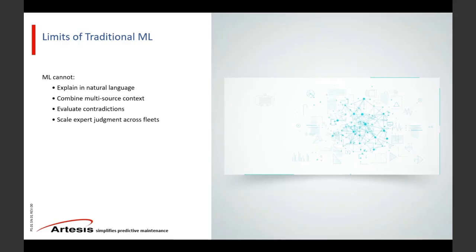It also doesn't automatically combine the multiple signals that our electrical signature analysis-based solution generates into one narrative. Meaning that you will sometimes have mechanical issues. You would see a bearing fault, but if that comes from fluting, which is caused by a VFD, it requires a more comprehensive look into multiple data sources to, again, create a single narrative. In real life, you're not looking at one trend in isolation. You're looking at spectrum, operating conditions, load changes, and process indicators all together, trying to connect them into a single coherent assessment.